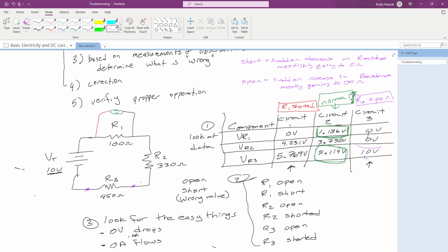We put huge resistance in the circuit, and that voltage is then going to drop across that resistance. Just basic Ohm's law. As the resistance increases, the voltage drop also increases. So if we slap in a value that's more than 100 times bigger than these guys, that voltage drop is going to go up 100 times that of the other component. So that's one way that we're going to use all of our skills.